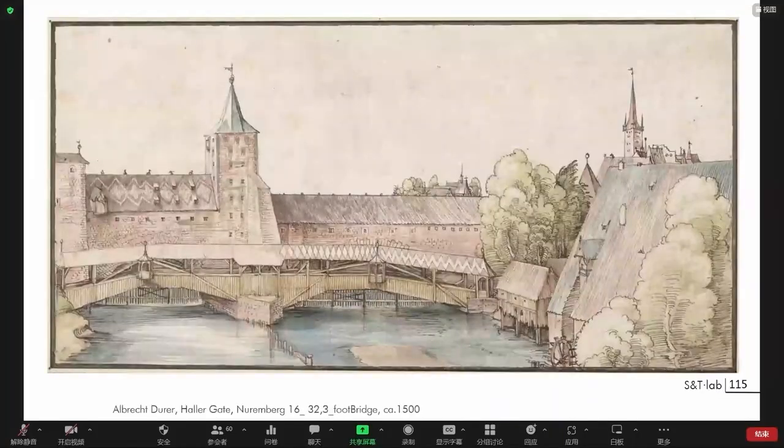If you are looking at timber bridges, you have this system that's quite old. That's another example in painting of the Middle Ages by Dürer, if you know this time. And you can see here an efficient system using funicular, but also protection of the timber with a roof, and also protection with a kind of facade on both sides to keep the rain from reaching the structure and making it less efficient with time.